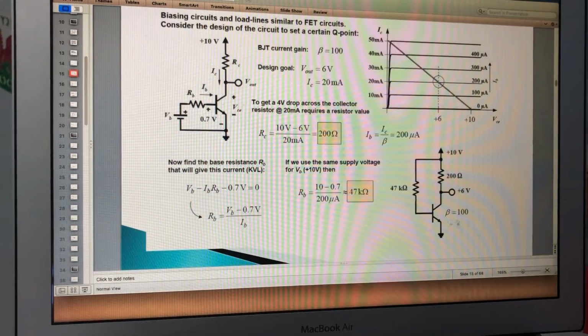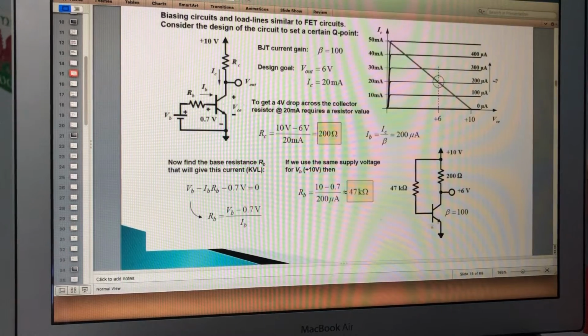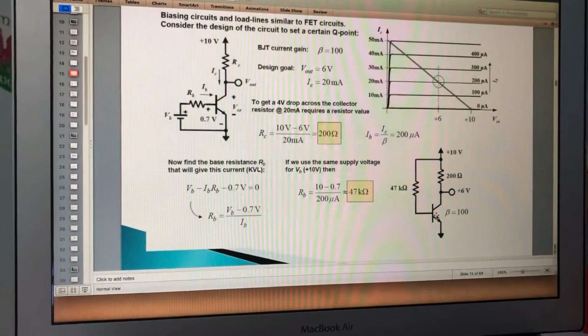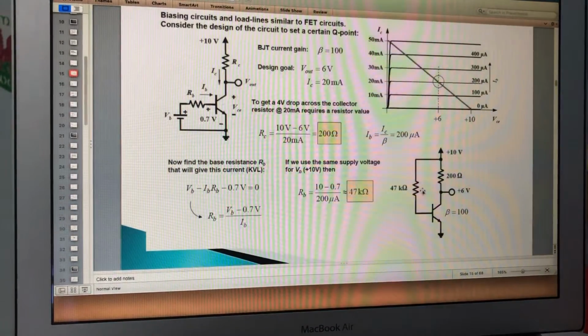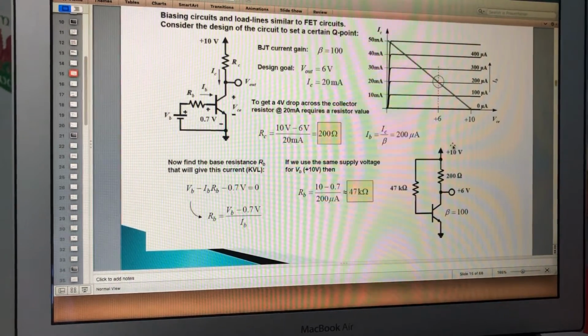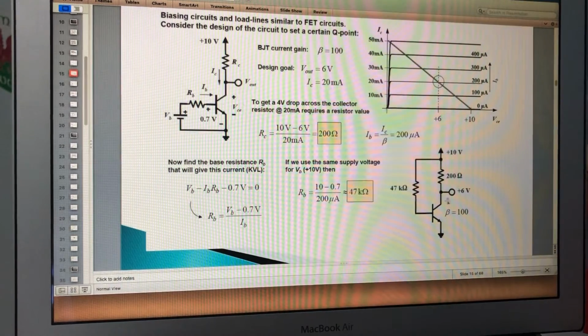So this is the complete circuit now. See, this is ready. When we put the voltage supply here with these two resistors, this transistor is ready to amplify signals. But there are no input signals yet. This is only biasing. I hope you understand. When you do this biasing, without any AC signals, it is already ready. We just want to bias the transistor to be in the forward active region. I hope you understand this equation.